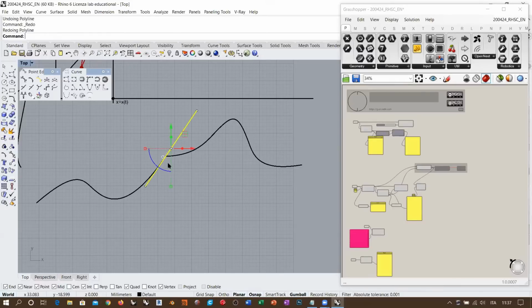And when we do this, we set tangency continuity, which is called G1. Okay, so G1 is the lowest level of continuity we need in order to avoid the presence of vertices in the connection point or along the connection edges between surfaces, or connection point between curves. So G1 is the lowest level of continuity that allows avoiding visible discontinuities. Okay, but this might not be enough.